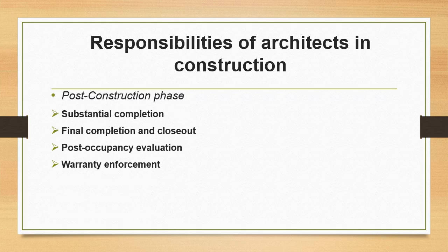Next phase is the post-construction phase, and the first responsibility is substantial completion. That is, the architect conducts a walkthrough with the owner and contractor to create a punch list of items that need to be corrected or completed. Upon completion of this list, they issue a certificate of substantial completion.